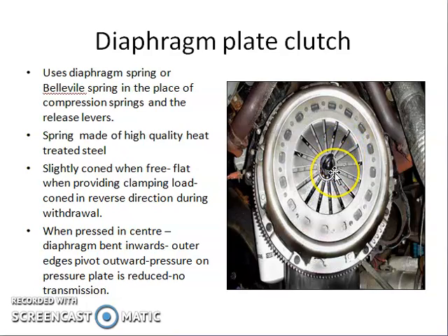Whenever the clutch pedal is pressed, the center portion of the diaphragm spring is being pressed, so it moves inwards, and then the pressure on the pressure plate is reduced. When the pressure on the clutch pedal is released, the diaphragm plate springs back to its original condition and becomes flat, and automatically pressure is being applied by the pressure plate onto the clutch plate.